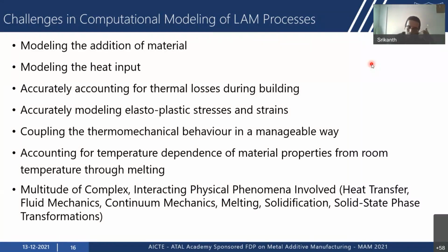So this leads to the evolution of residual stresses. And to predict residual stresses, we should be able to accurately model the elastoplastic stresses and strains. And now, prediction of residual stress needs a thermomechanical simulation, not just a transient thermal, but a thermomechanical simulation. So the question is, how do we couple this thermal and mechanical behavior in a manageable way?